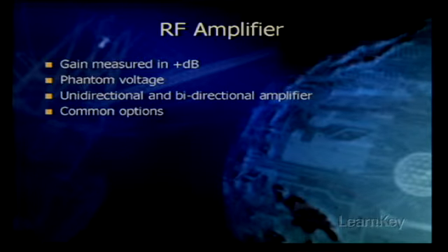The other thing that's very important with the amplifier is that it needs to match impedances with all of the other wireless LAN hardware between your transmitter and your antenna. Generally, the wireless LAN components have an impedance of 50 ohms. However, it's always a good idea to check the impedance of every component of the wireless LAN before you actually purchase your amplifier. Last thing that you want to have is an issue with output power.